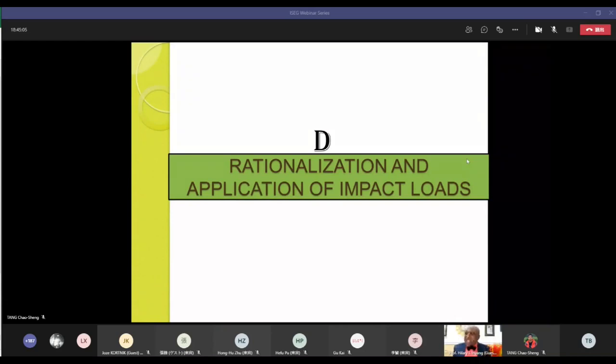So the next section deals with how we can apply impact loads while at the same time cutting. The purpose of the impact loads that hit the surface of the rock is to create cracks on the rock surface, while the cutting bit then comes into action. And its action will now be with much reduced force because it doesn't need a lot of force anymore. The rock is not as intact as it was before.